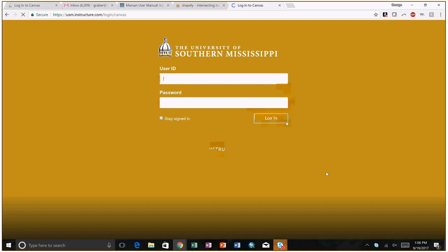So the UTM coordinate system has an origin, and it's expressing your distance in meters north from the origin and the distance in meters east from the origin. So if you're right here, you could be 3 meters north and 2 meters east. Okay, so the east is the x. We call this the x, and the northing we call y.